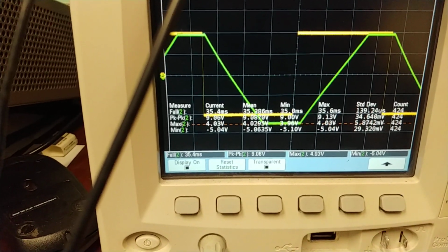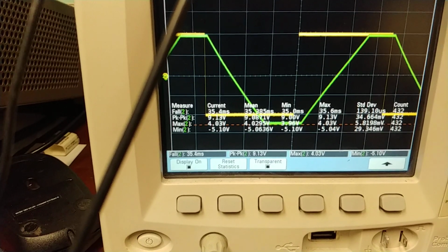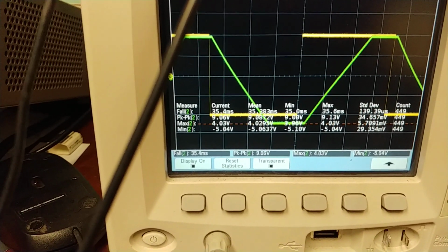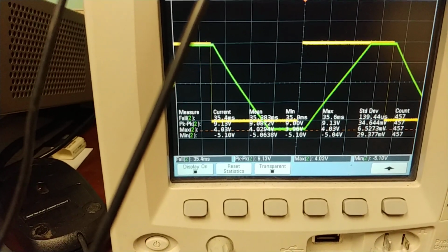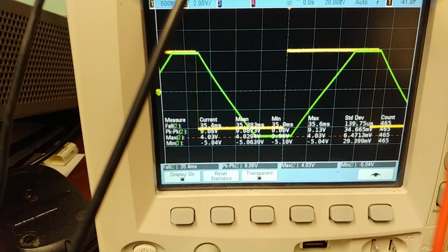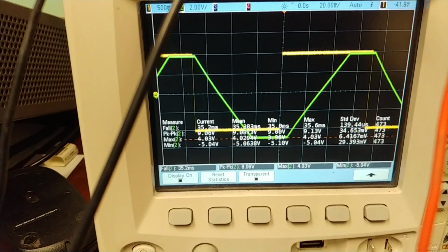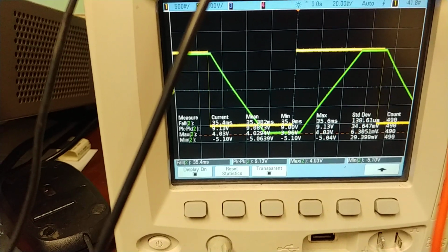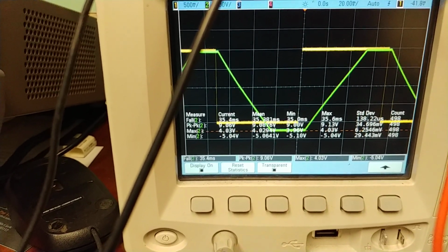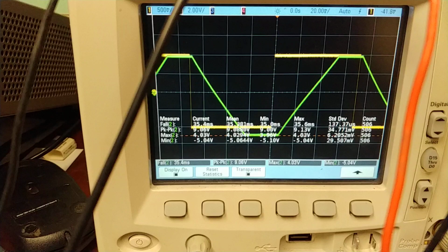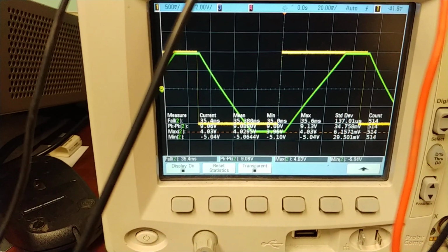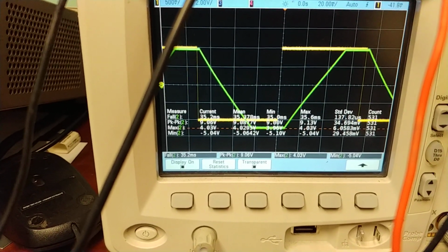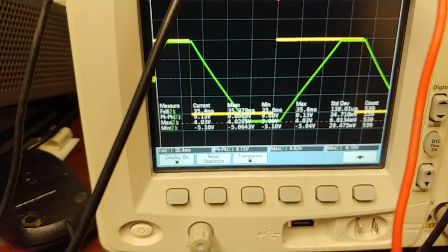I did have to adjust the bottom power supply so that the minimum was coming out closer to 5. That's not too much of a problem. And the initial condition is sensitive to the power supply voltage. So maybe if I were to make this circuit more reliable, I would use a voltage reference and go from there rather than depend off of the raw power supply voltage.